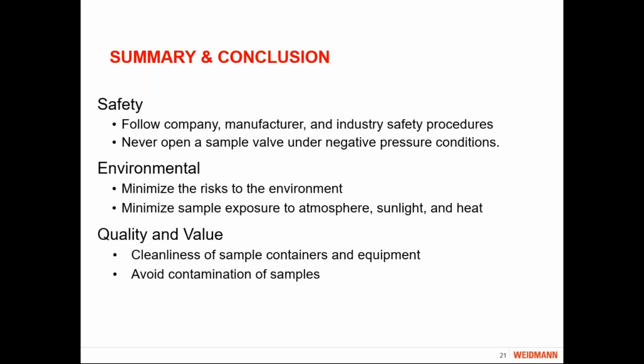Never open the sample under negative pressure conditions. I think I might have mentioned that once or twice already. Never open a transformer that has pressure under vacuum, because you want to avoid pulling in contaminants and especially air bubbles in. So if it's negative, don't open a valve, don't crack a fill valve to vent air. Don't do any of those things. As I said, you need to do something to repressurize it, whether adding gas or heating up the oil so the gas space gets compressed. But do not open the valve under any circumstances if you're under negative pressure.